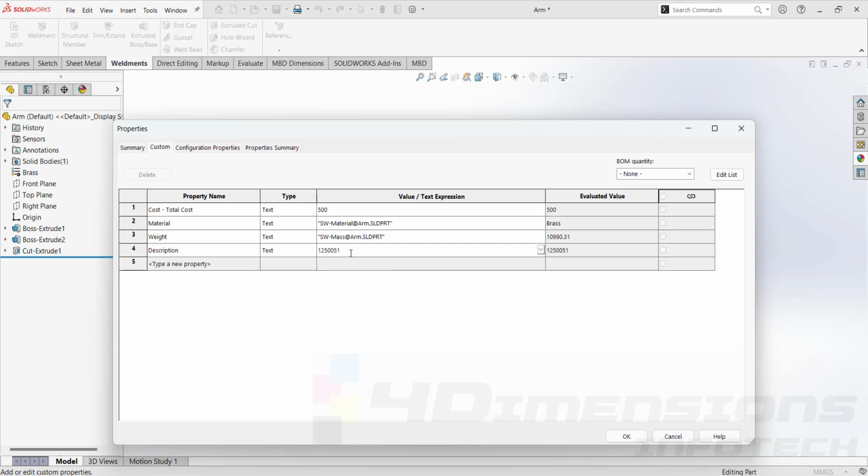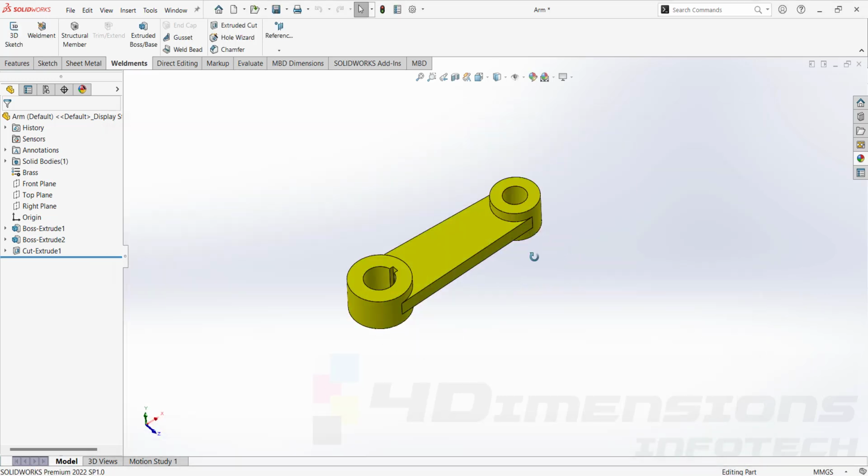In the actual process, in the description we are going to provide the name of that part, and the part should be saved by the number, this number that is generated by the company according to the parts. But instead we have done the reverse thing. In description we are showing the number, and actually while saving we have saved the name here. Say OK. Again we'll save this part, say save part, and then move to assembly again.